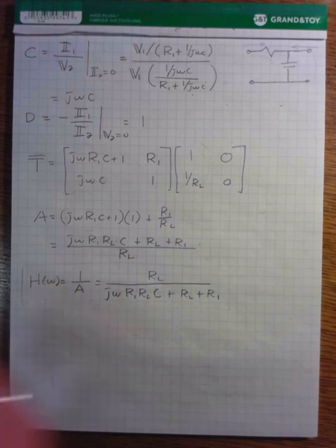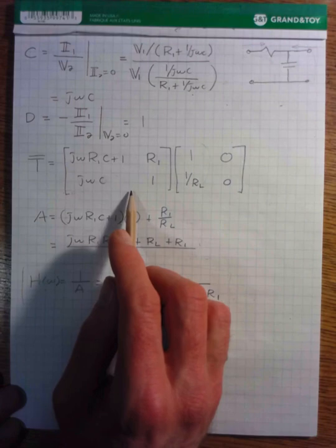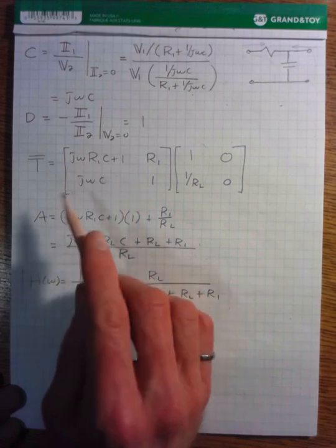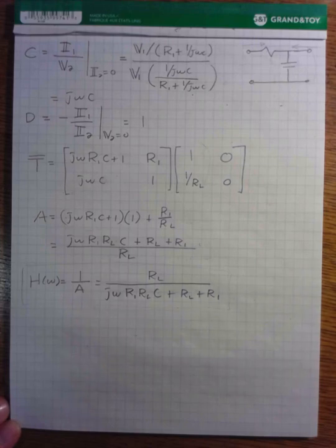And in particular, if you substitute in numbers here, like we did for our resistor analysis, you can cascade a huge number of matrices together if you're doing the matrix multiplication in a package like MATLAB, for example. And so that's really the efficiency of using these transmission parameters.